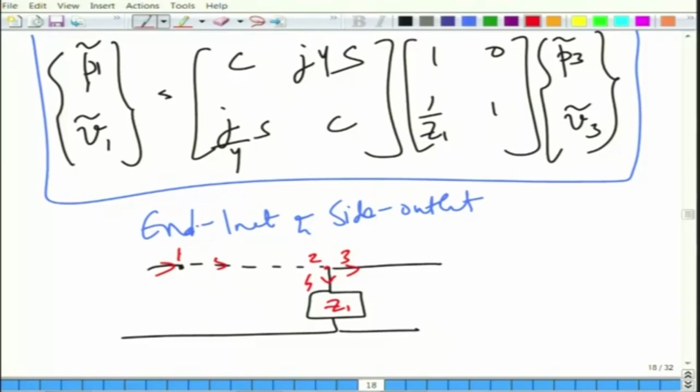So, what does acoustic reciprocity mean? Basically, if you change the positions of inlet and outlet, that is, if you excite a system at a certain point and measure the response at another point, and keep the response aside and do the reverse, that is, the receiver point now becomes the source point, and where the original source was becomes the response point, you see the response functions in each case are identical.